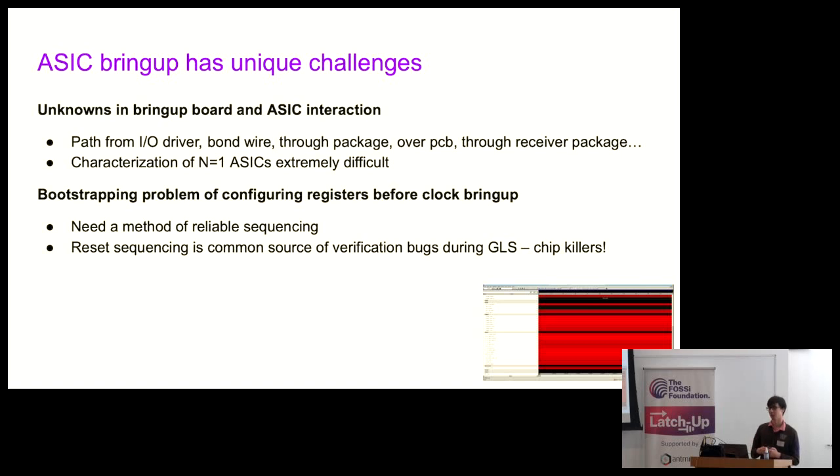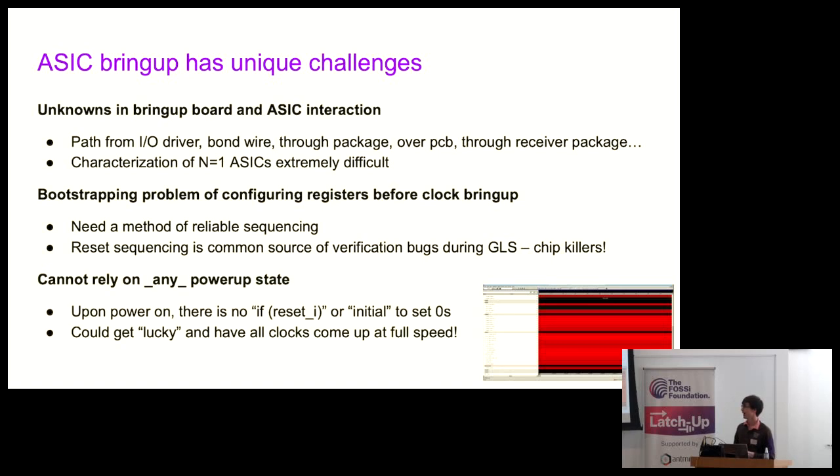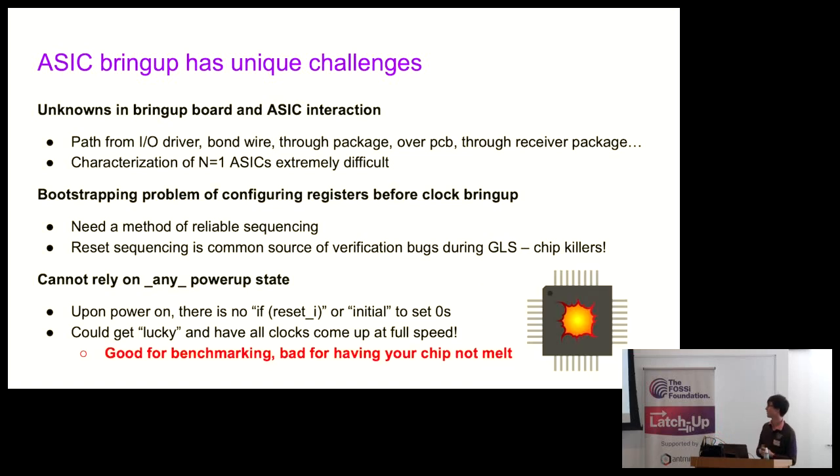You also have a bootstrapping problem that doesn't normally exist on, say, an FPGA, where you need a reliable method of sequencing your power and reset and clocks so that the chip comes up in the correct way. And notably different than FPGA is you can't rely on any power-up state. You can have power on, there's no reset or initial that just happens when you turn on the chip. You need to have that explicitly in the sequencing. You could get lucky and all your clocks for all your designs could come up at full speed, which is great for benchmarking, but it might turn the chip to glass.